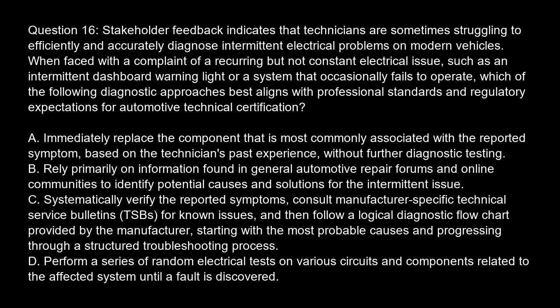Option C. Systematically verify the reported symptoms. Consult manufacturer-specific technical service bulletins, TSB, for known issues, and then follow a logical diagnostic flowchart provided by the manufacturer, starting with the most probable causes and progressing through a structured troubleshooting process. Option D. Perform a series of random electrical tests on various circuits and components related to the affected system until a fault is discovered.